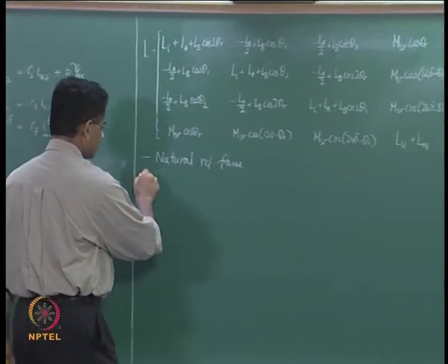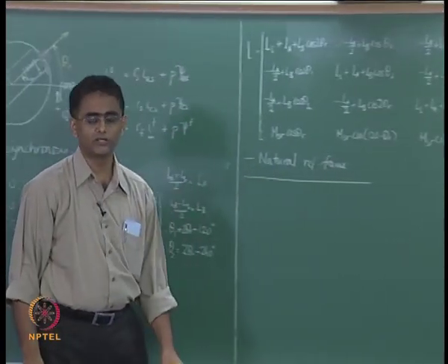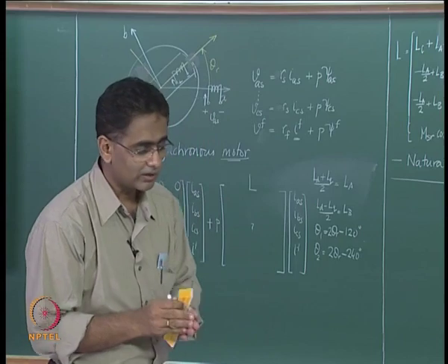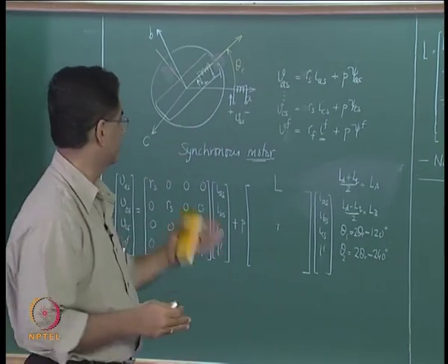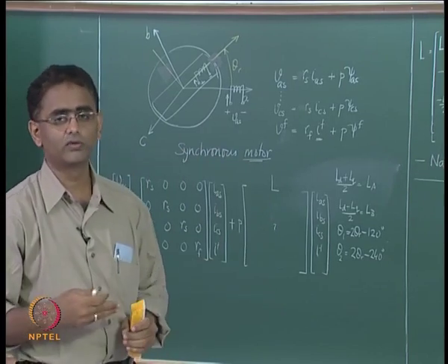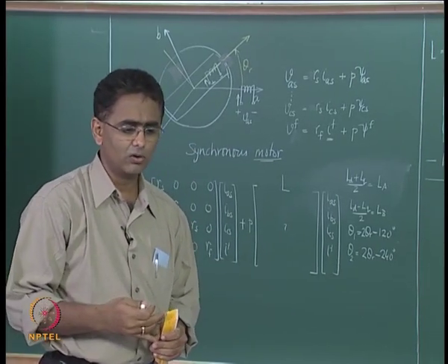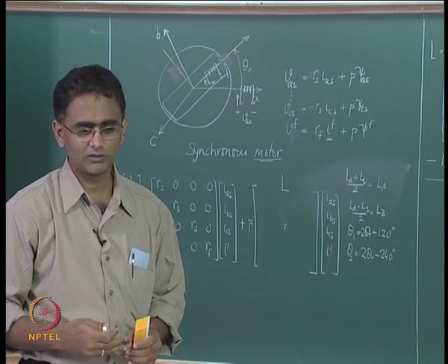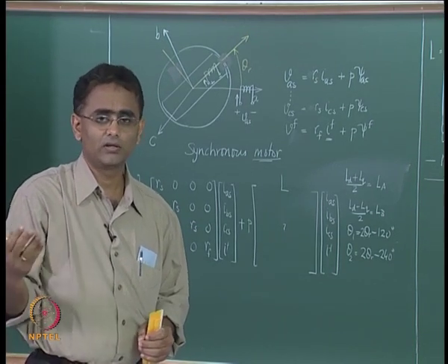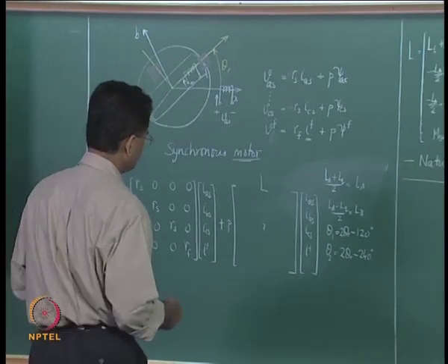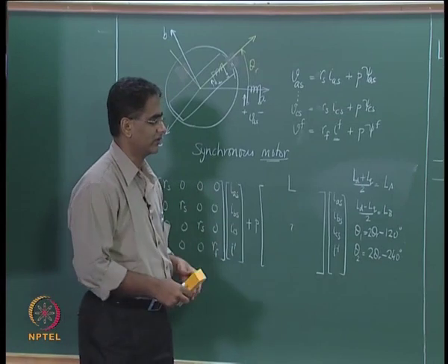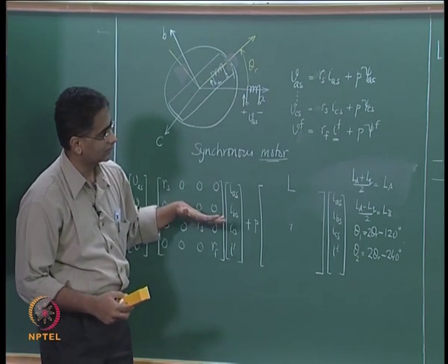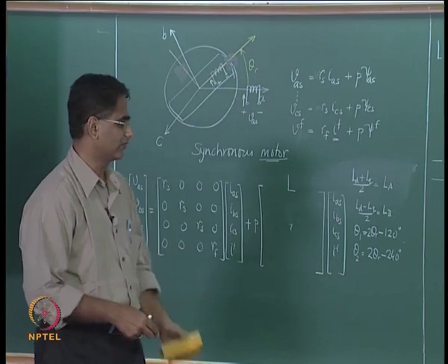Now the synchronous machine is rarely analyzed in this reference frame, and the synchronous machine rotates at only one particular speed, that is the synchronous speed, and therefore the only frame of reference other than the stator attached natural reference frame which may be of use is the synchronous reference frame. The arbitrary speed reference frame is not of much use, or any other frame of reference. By and large it is only the synchronous reference frame that is used, and therefore in order to look at those equations, we need to transform these equations into the synchronous reference.